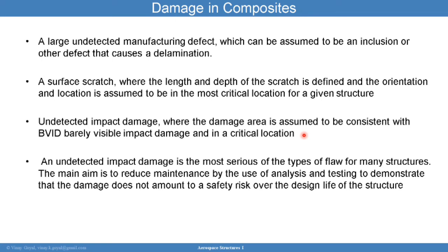approaches. Repairs can be done to basically look at fixing those areas where delaminations occurred or fiber failure occurred. Fiber failure is hard to really detect through non-destructive evaluation, where delamination is a little bit easier to examine. I do have a YouTube video lecture on repair processes that's worth watching.